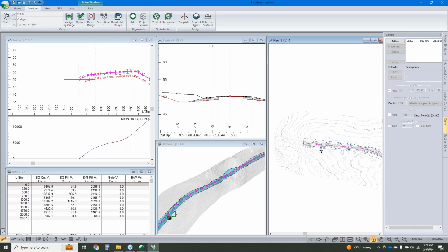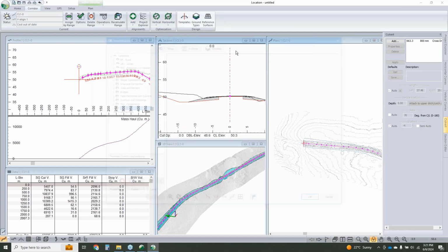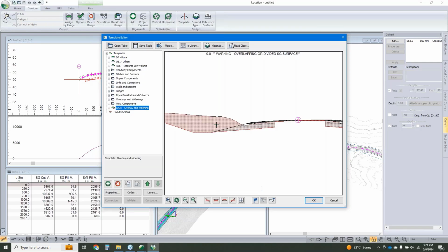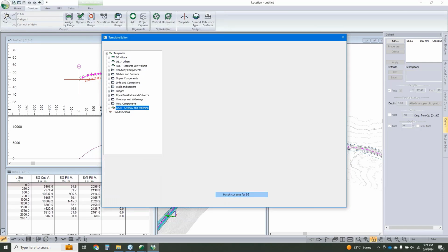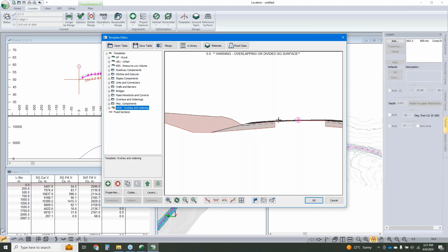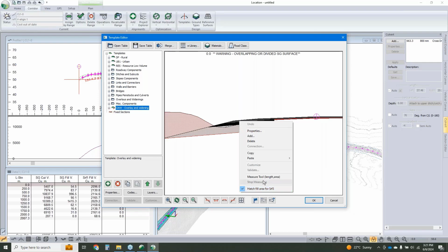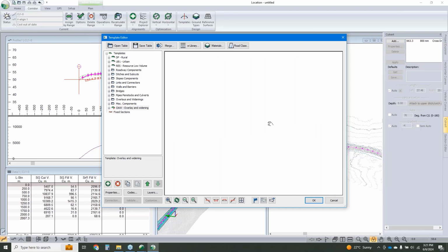One thing that I will just kind of mention that comes up every now and again. For this, my volumes are split out. So for this, if I go in here, I can see I've got my subgrade being tracked as kind of the portion of my cut outside of the existing prism. And then I've got SRF1 as our fill. I've got SRF4 as my sub base versus base versus ACP is 3. So when we look at our data table, we can see those various items being called out.